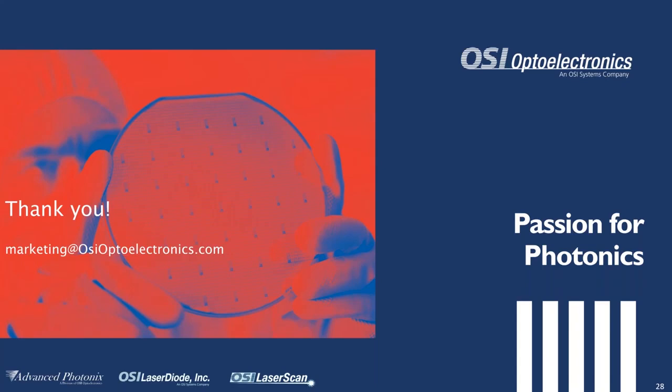Thank you. Is the gain bandwidth different for a 2.5 APD versus a silicon germanium versus a silicon APD? Well, actually, it's not very different. Again, it depends on many structural parameters of APDs, and even different silicon or silicon germanium APDs may provide different numbers. So I would say that it's not much different.